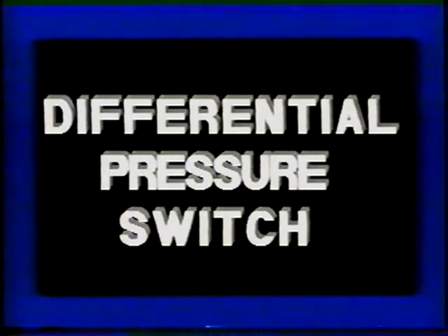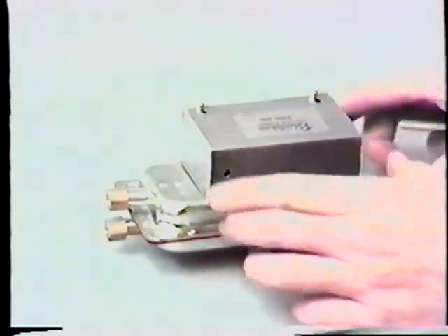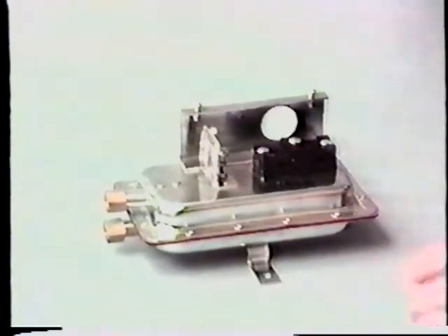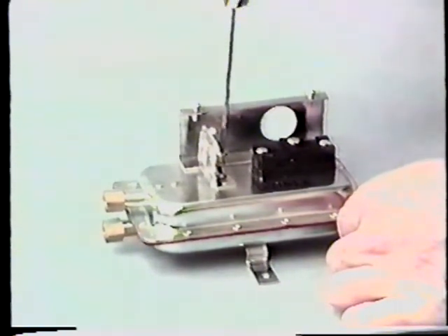The differential pressure switch is a very sensitive pressure-activated device for sensing the operation of fans and blowers. It is also used to sense static pressure drop across filters to actuate an alarm indicating when they are dirty. The differential pressure switch operates at very low pressures. It operates in the 0.05 to 12 inches of water column range and activates a single-pole double-throw switch. This pressure switch can be adjusted to activate at any pressure throughout its range by turning the adjustment screw.